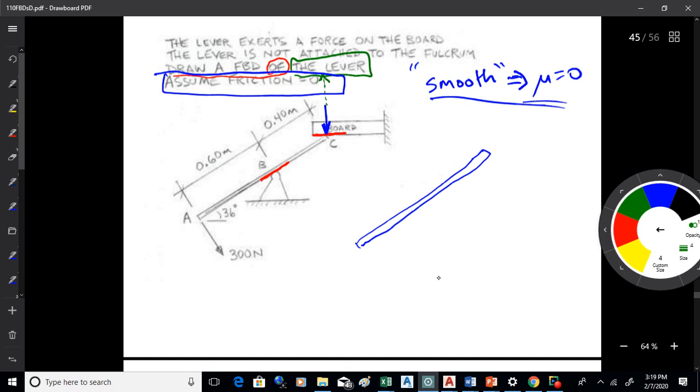Okay, but what you cannot do, you can't have a force like this. If you guessed the force was doing that or even this, you would not get a right answer. You just wouldn't get a sign you had to flip around. You'd get an incorrect answer had you assumed that, because the force has to be normal to the flat surface. So it has to be a vertical force. Established your axis along the line of the thingy, right? If you cause your x-axis at an angle, then it might come out okay. No, it has to be a vertical force regardless of how you set the axis up. Okay? So it has to be straight up and down. It can be up or down, but it can't be at an angle. It won't come out right if it is.